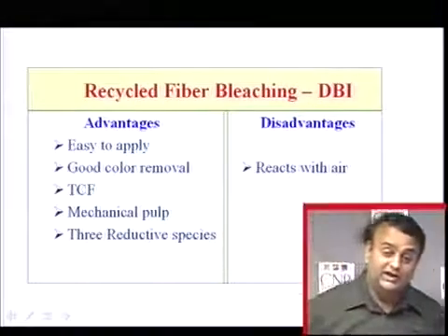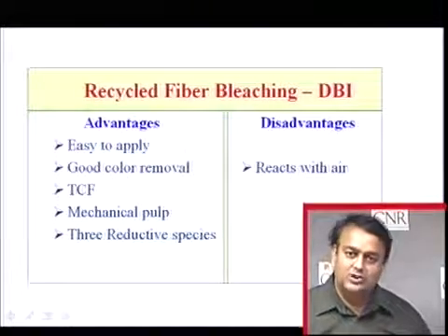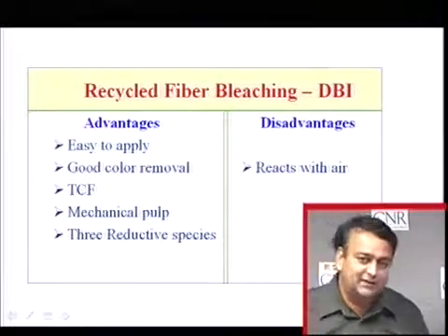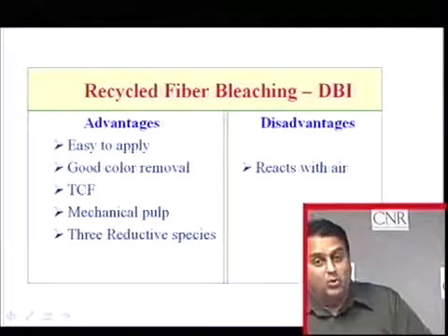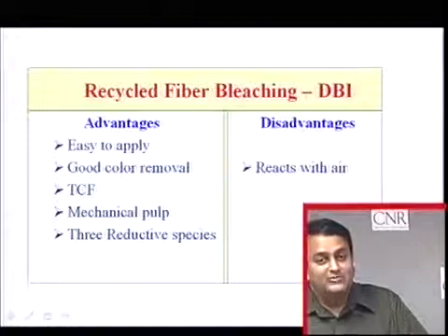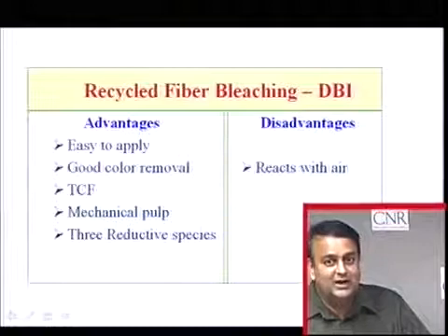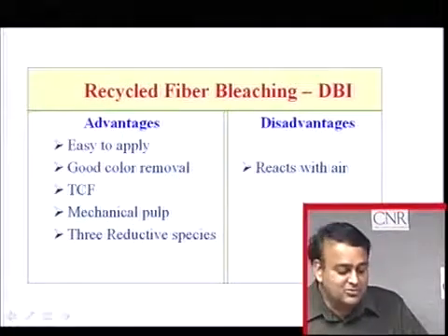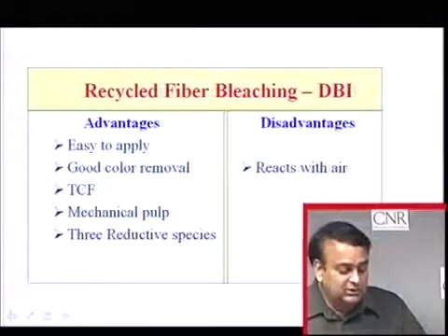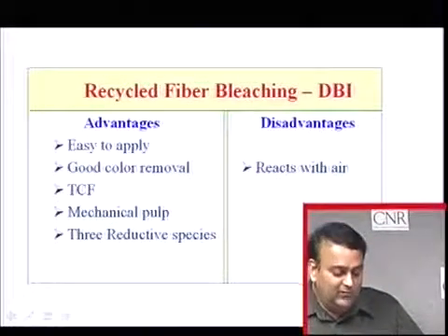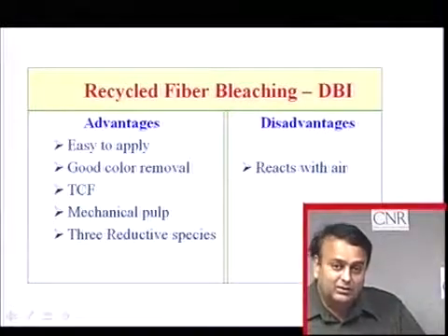What are the advantages of DBI? Very easy to apply, because these are two liquid systems. There are two pumps. You just pump it through the static mixer, and there it goes. Excellent color removal. Sodium borohydride is a very strong chemical. It attacks double bonds, particularly in dyes, and it works on those dyes and removes them. Well, azo dyes.